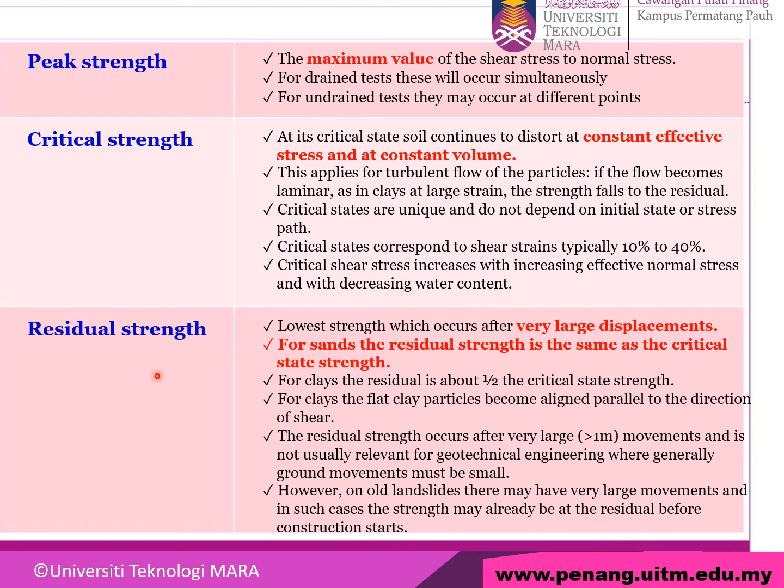How about residual strength? It is a lower strength that occurs after very large displacement. For sand, residual strength is the same as the critical state strength. Residual strength occurs after very large movement, for example more than 1 meter, and it is not usually relevant for geotechnical engineering, where generally ground movement must be small.